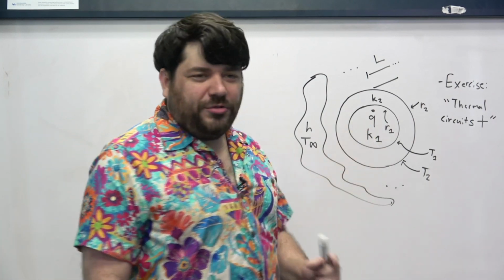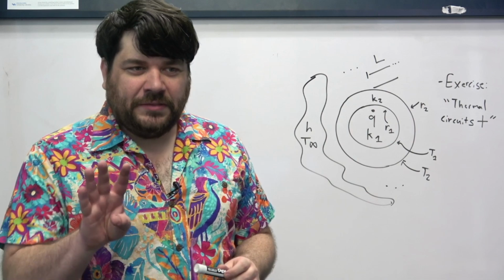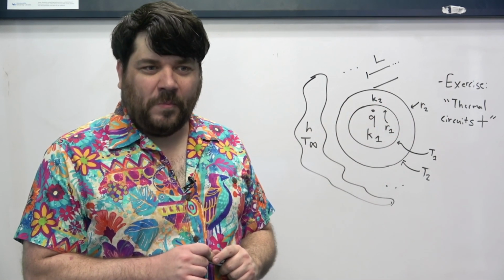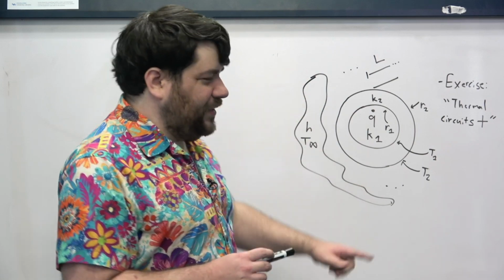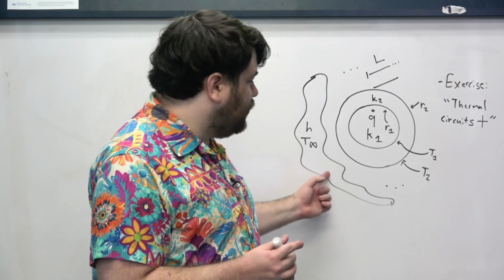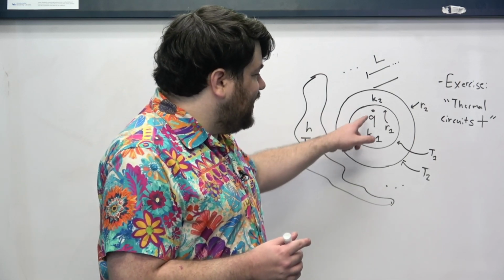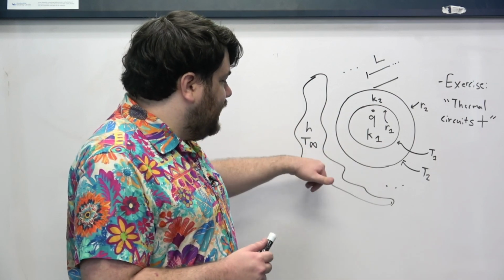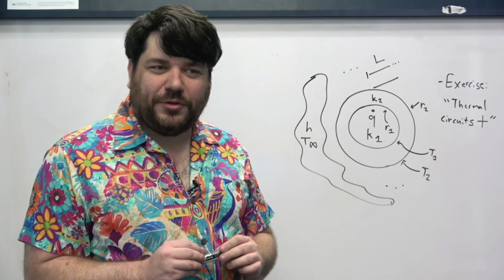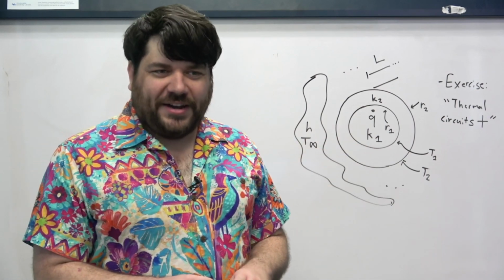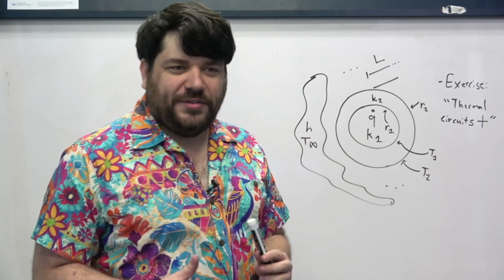This inner portion doesn't satisfy the four assumptions, but the cladding does, and the environment does. So why don't we model this like a thermal circuit that's connected to this goofy Q dot? Why don't we model the cladding and the air as a thermal circuit and then just add in this goofy little Q dot on one of the sides of the system?